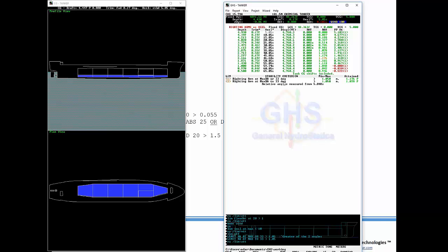Whereas the maximum righting arm occurs here at 46.6 degrees, 1.176. So the first limit is actually taking the greater of the two angles, whereas here it's taking the lesser of the two. Max to 33 degrees is actually taking the lesser of the two, which is in this case 33 degrees. That's why the or and to keywords are contextual.